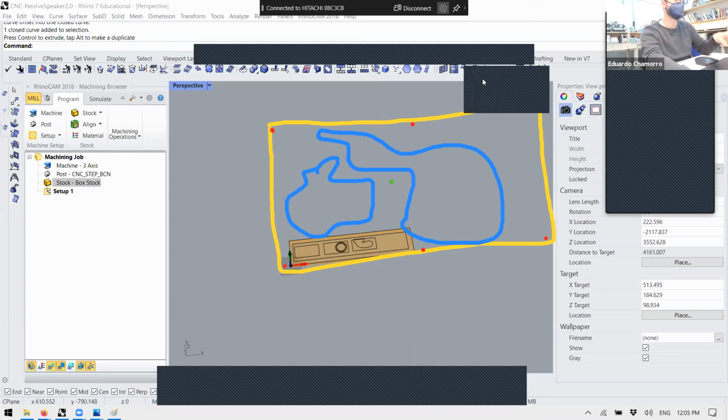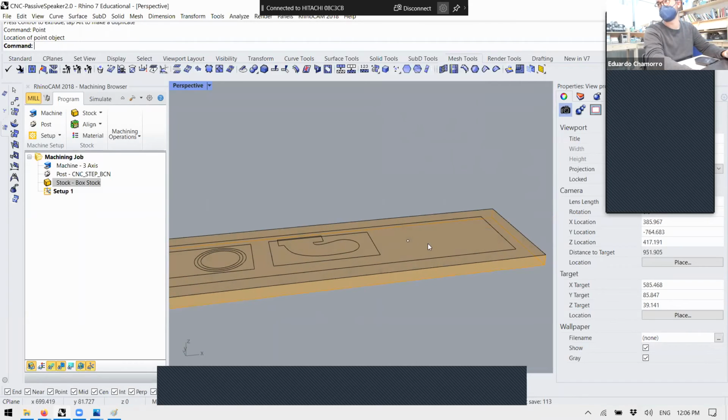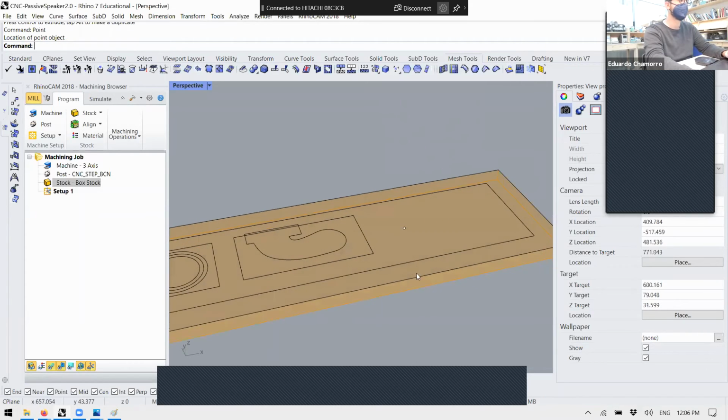Ideally, what you do is design your screw in the file. You make a point, and check that your point is in the Z0, which is important, and we will produce an engraving. Before launching our file, we will touch 1 millimeter and the machine will stop, because it won't be a file just with touches on the material. The machine will stop, we go on the machine, we put the screws in the location, and then we launch the file. So we are sure that is the best way to never touch a screw.